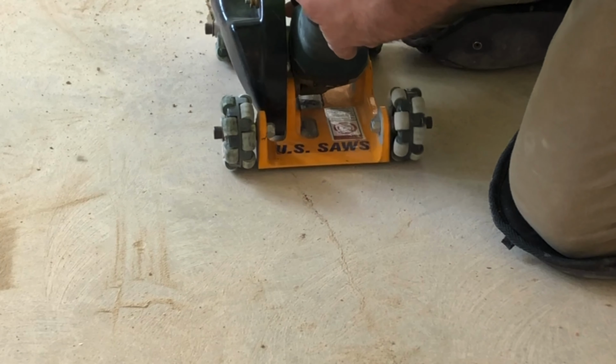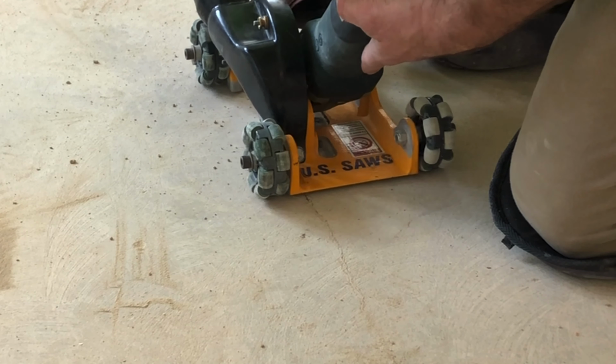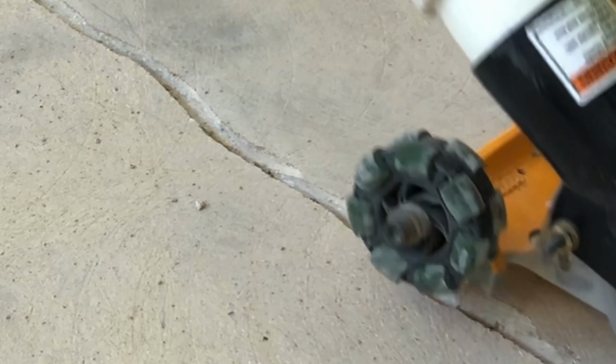So if I want to cut a crack to not only open it up and remove the micro cracking that we expect to be there, there's a good chance that that saw blade is going to have to navigate the angled shape of the crack, because the crack doesn't run in a straight line. So what we end up with is a crack that probably is going to be a little wider. The cuts might be a little further out than we anticipate. But if we're trying to chase those sidewalls and get rid of all those micro cracks, then we might end up with something that looks like kind of a nasty cut in the concrete. But our objective, again, is to prepare the sidewalls of the crack and also get rid of any of the microfracturing that can reasonably be expected to exist.